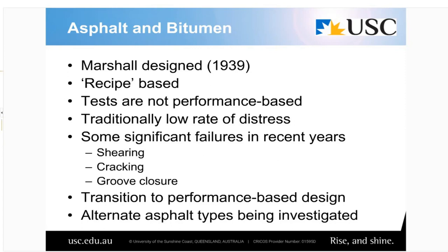These are things that we hadn't really encountered in significant ways in the past, and they have led to a transition towards more performance-based testing and more performance-based asphalt design, and even now to alternate mixtures, sort of disregarding Mr. Marshall's traditional recipe-based mix and looking at some other types of asphalt that might be more appropriate, that have been developed in Germany and the rest of Europe in the last 40 or 50 years.